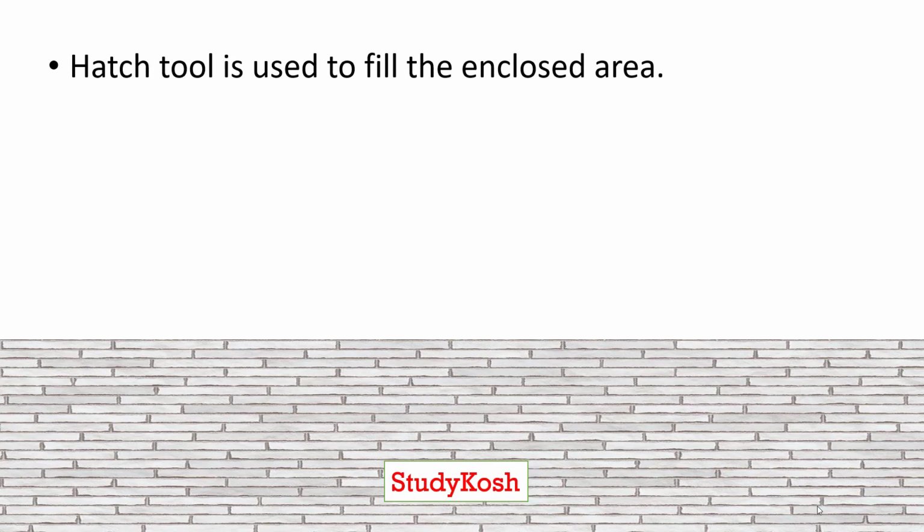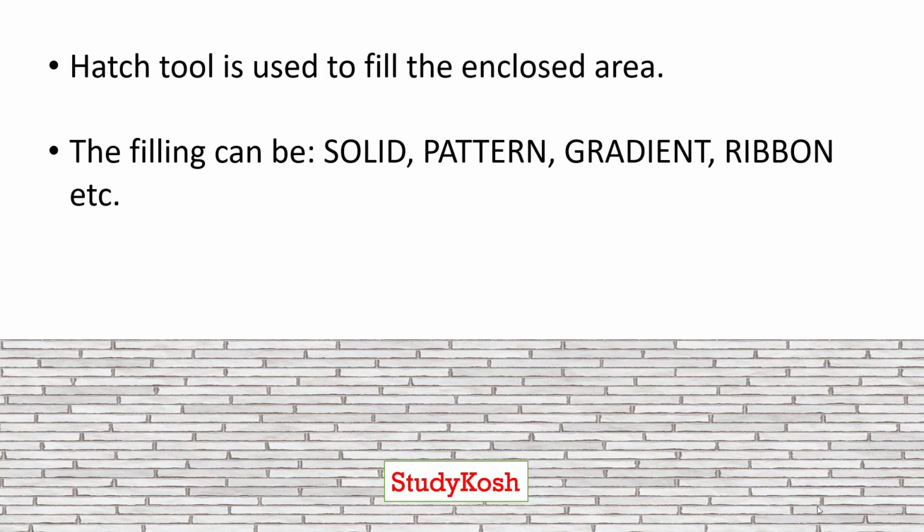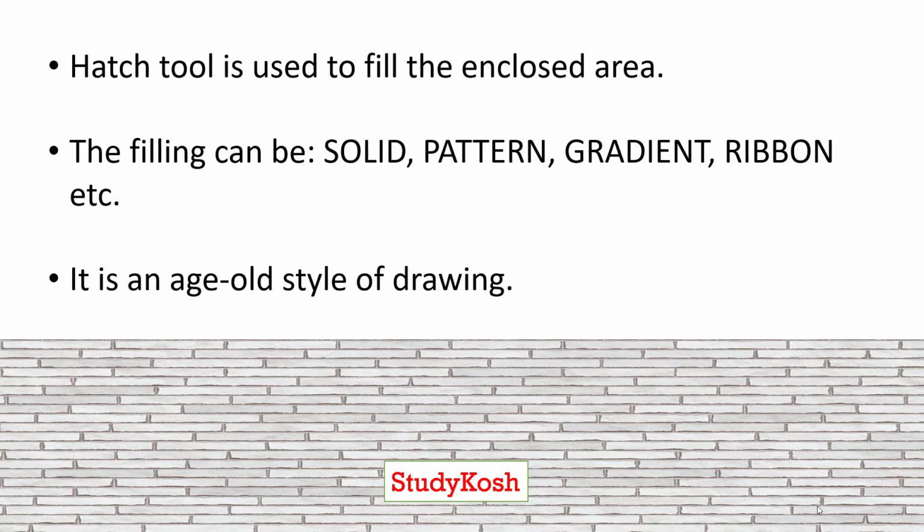But before knowing how to apply hatch on walls, let us first see hatch tool is used to fill the enclosed area. Always know when you are drawing something in AutoCAD, if it is not a closed loop or the area is not enclosed, you cannot apply hatch tool. The filling can be either solid, pattern, gradient, ribbon, etc. It is an age-old style of drawing.